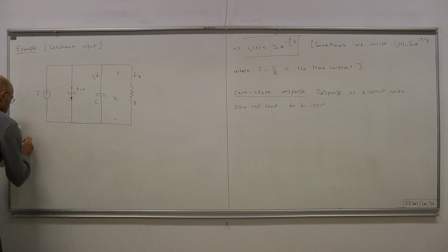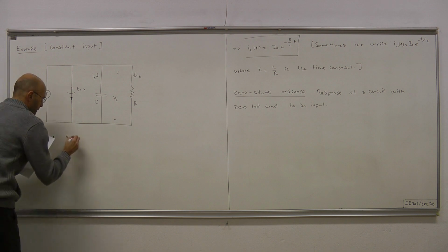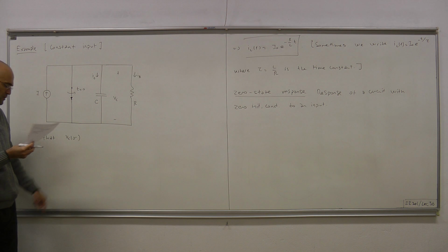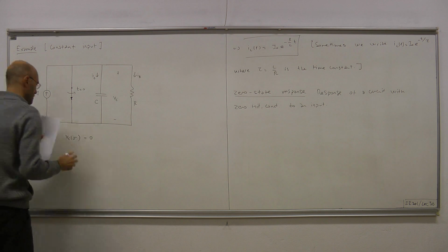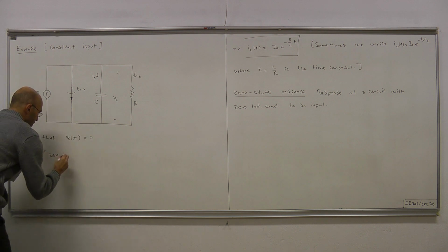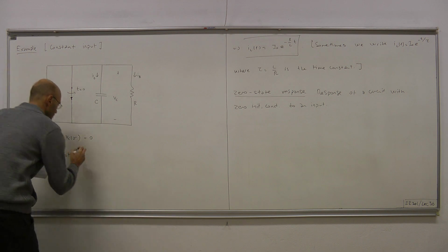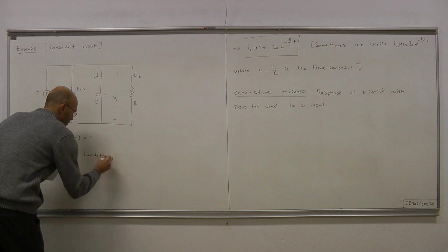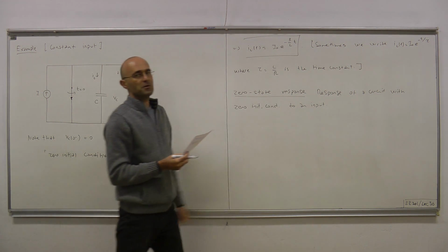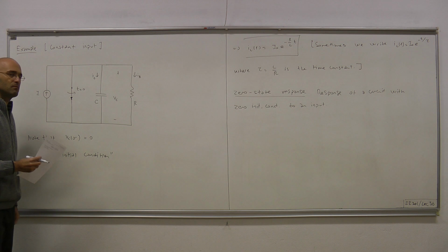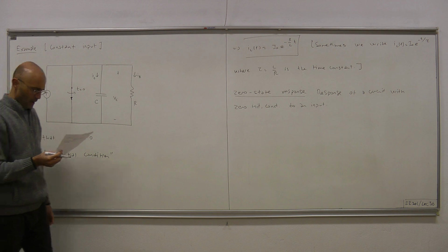But first, note that the initial capacitor voltage VC(0 minus), just before the switch is open, equals 0. That's why we can say that this is a circuit with zero initial conditions. And hence, what we're dealing with here is zero state response. It matches that definition.